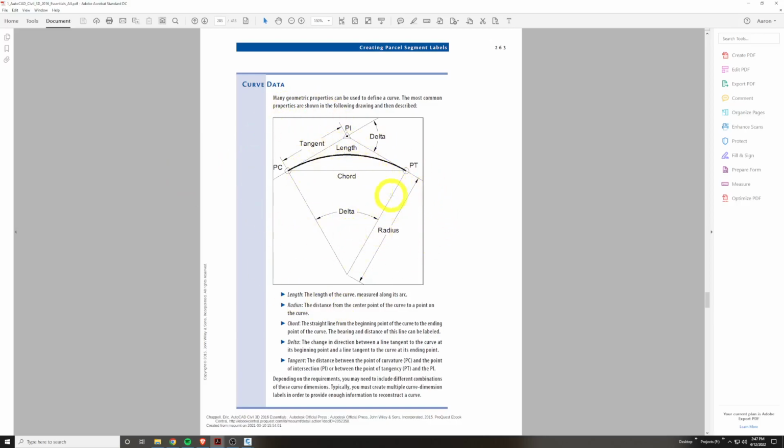This is something to really hone in on and memorize for the geometric properties of proper civil and land surveying design. If you can do this, you have non-tangent ones where this is no longer 90 degrees. Anything but 90, it is non-tangent. So it could be a small 1 degree off, it is non-tangent. That happens when you're trying to field fit surveys or for various other reasons, but this is ideal.